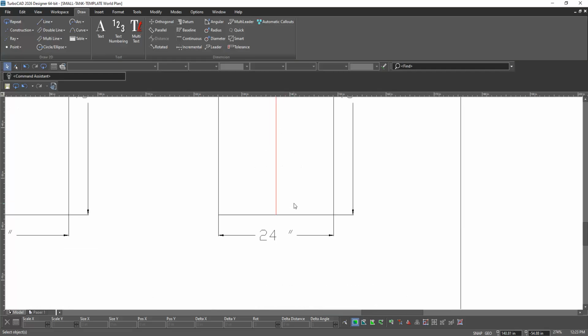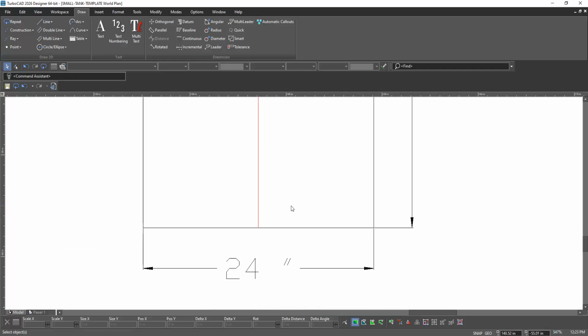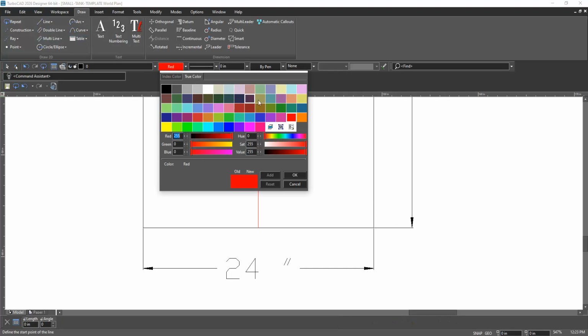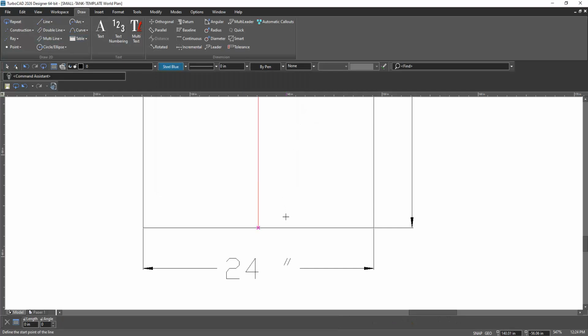I want to zoom in down here, and I want to do another temporary line, and this temporary line we're going to make it blue. So where that's red, let's just select a blue color, any blue color you want, go right here and go up, pull upward, go tab, hit 1 inch, and angle, type in 90, 1 inch and 90.